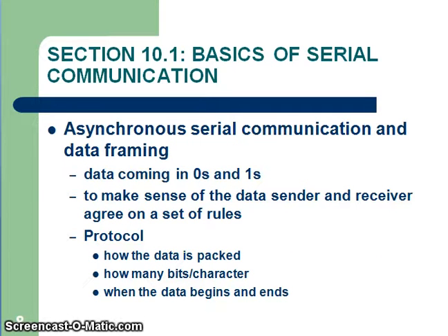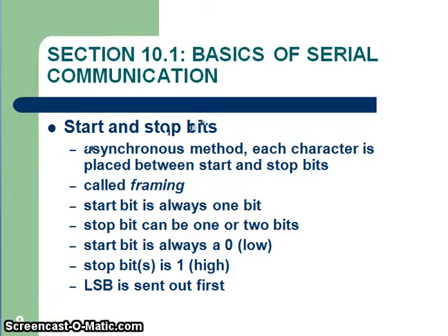Asynchronous serial communication and data framing. We are transmitting data as zeros and ones. To make sense of the data, the transmitter and receiver agree on a set of rules, protocols: how data is packed, how many bits of data per character, and when the data begins and ends. So a framing concept is involved: start and stop bits.